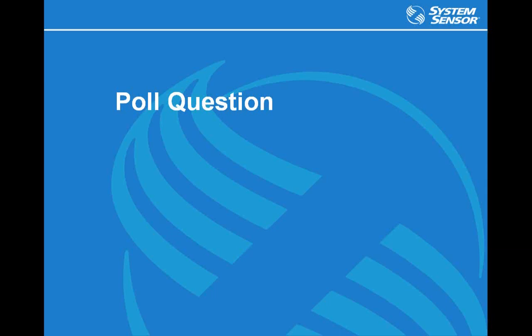This attendee is asking for maybe clarification. His AHJ talks about audibility versus intelligibility, and he wonders if we want to describe what the difference is, or if he needs to educate the AHJ on the difference. Well, audibility is just the dB output of your speaker, or the dB that you're getting in your environment.